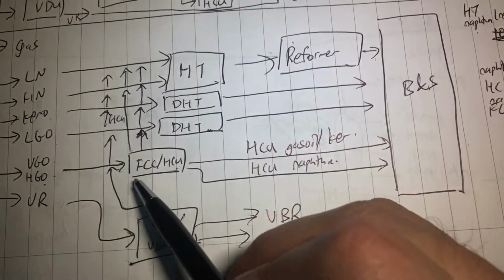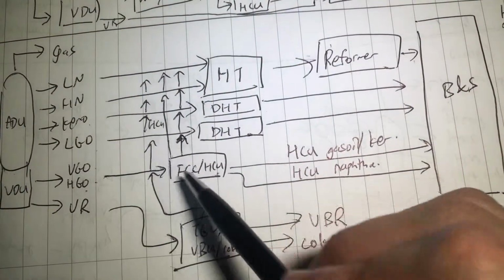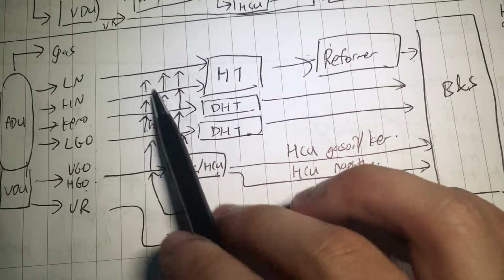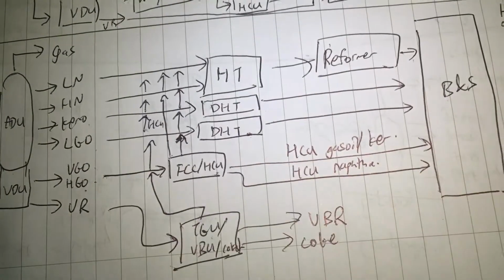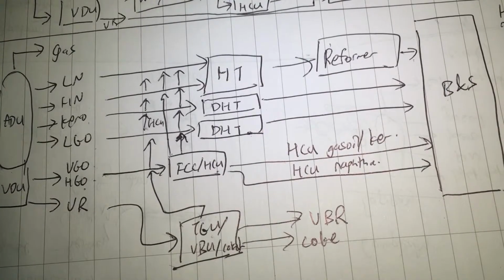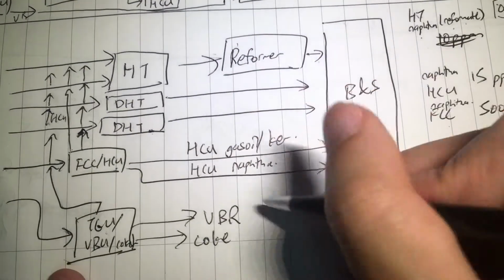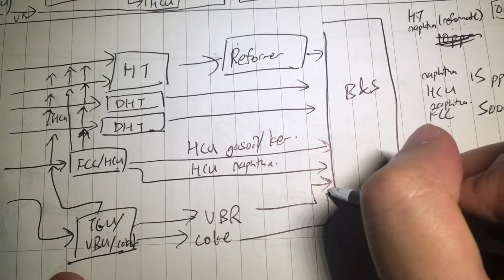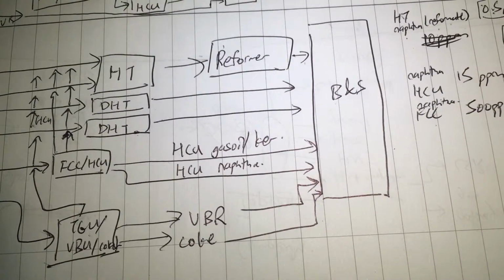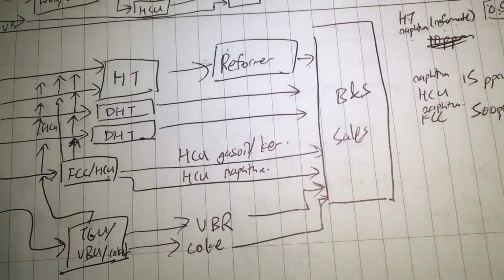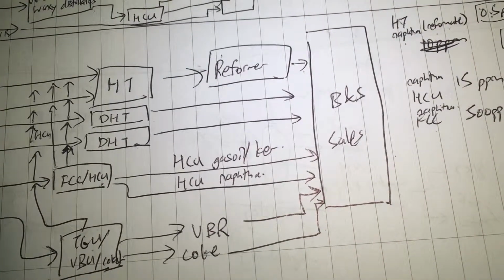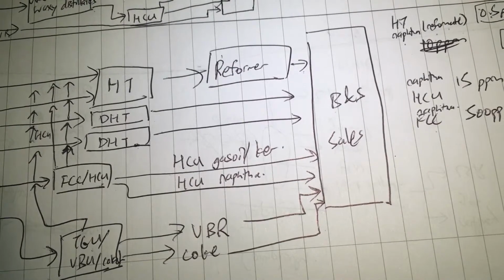Then, of course, I'll send whatever is relevant here, the coker gas oils, the vis broken gas oils, naphtha, all here to be hydrotreated to get it saturated and everything ready for blending and storage. So this will go into the blending and storage, and of course, you don't blend coke into anything else, but you can actually sell it. There are a number of other things you can do with coke. I didn't discuss it, but it's on purpose because I want to simplify things.